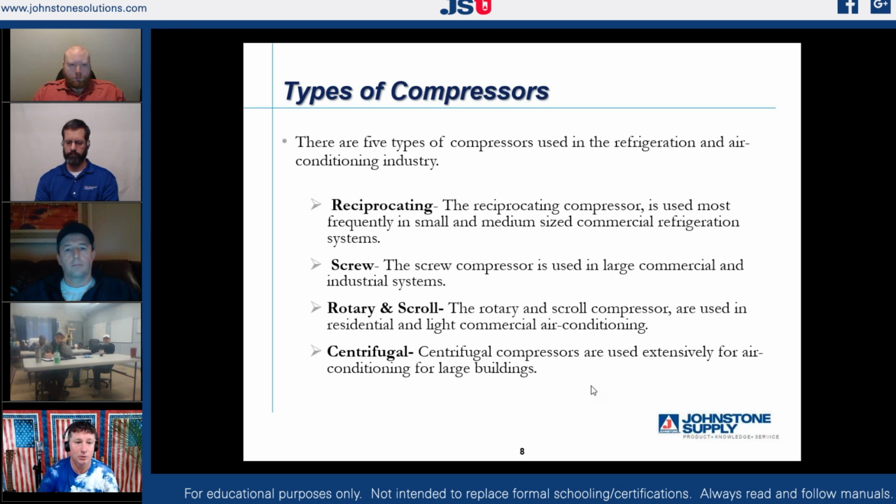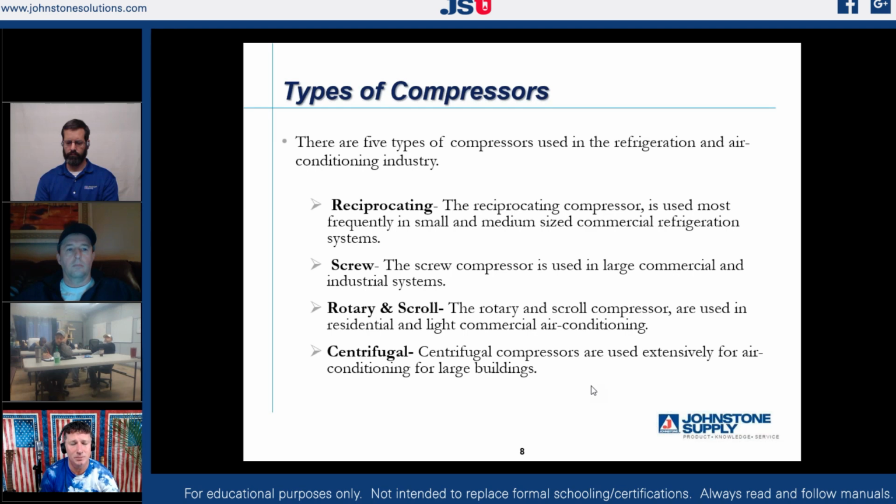You know, they're getting fewer in between, but they are around. Most of your residential refrigerators, the entry line refrigerators, are still using reciprocating style compressors. Light duty refrigeration is using reciprocating. I'm not aware of too many reciprocatings in our unitary equipment, but there could be. We want to talk a little bit about screw type chillers, commercial compressors. We want to talk about rotary and scroll, because there's a big difference between the two of them. We want to look at that.